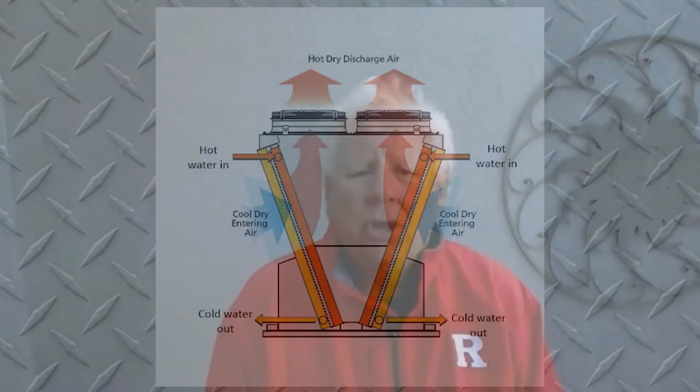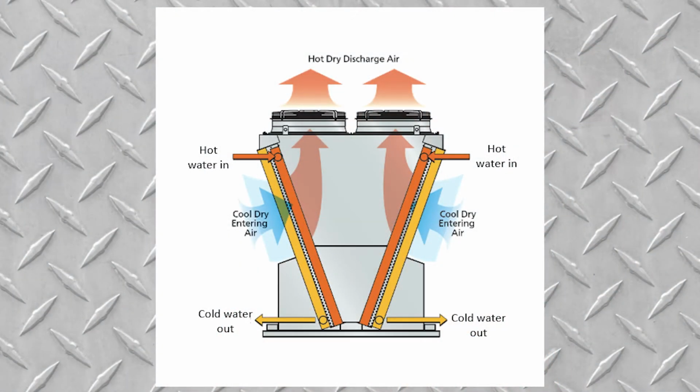Air-cooled chillers or dry cooling towers have the distinct advantage of having no direct contact between water and the air. So the water stays very clean and you're not going to have to worry about anything unwanted entering your plant. You simply bring in water through a radiator and put it back out again. You can see in the figure that the hot water usually comes in at the top and cold water leaves through the bottom. It's just a regular heat exchanger.